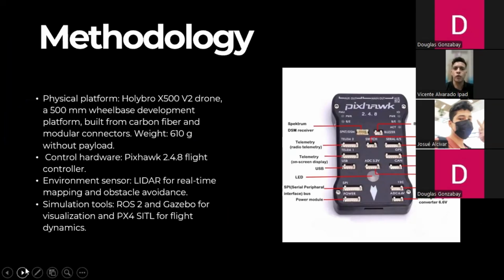We use ROS2 as a middleware to manage communication between the drone and the simulation. We use Gazebo to visualize the drone's 3D flight and test its kinematics and dynamics. We also integrated QGroundControl for mission planning and monitoring, and tools like RViz can be used for visualization of sensor data. The drone model was the X500 equipped with a PX4 flight controller.